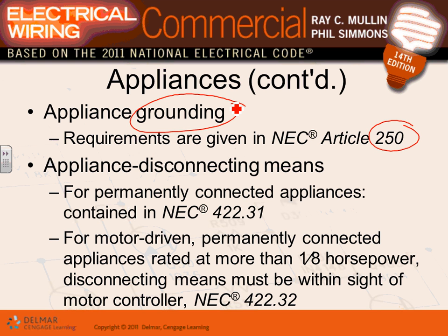So if they're three phase, they have to have 4 wires coming to them, 3 phase and a ground. If they need a neutral, they will have 5 wires coming to them, 3 phase, neutral, and a ground. Does that make sense? All of them, typical.